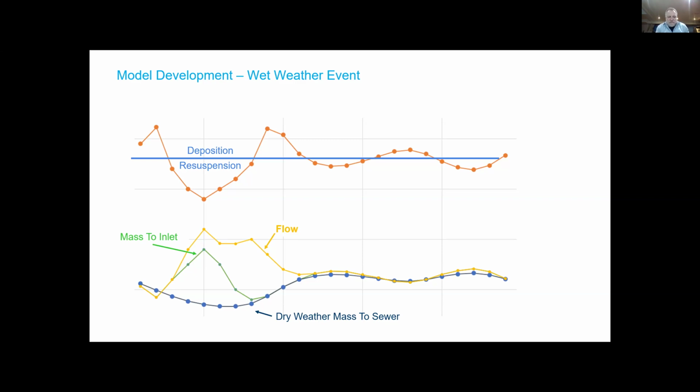So if that stuff has been sitting in the sewer for 2 weeks digesting away, it's going to contain a whole bunch more ammonia that's trapped and released as soon as a big storm comes through. You're going to have more volatile fatty acids in that material, and that kind of thing happens. And so the nice thing about the conceptual idea of this model is that it satisfies all of the ideas that are required in order to predict the behavior of the treatment plant.